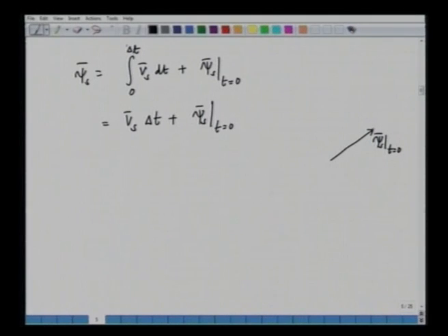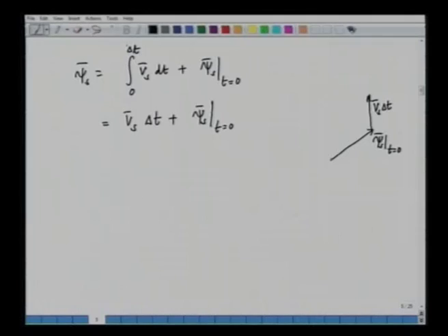and we have applied some voltage vector, that is Vs into delta t. Remember, time is a scalar quantity, not a vector. So, Vs into delta t will have the direction of the original Vs, and Vs is one of the 8 voltage vectors. If we complete this vector triangle, we will get the resultant here.